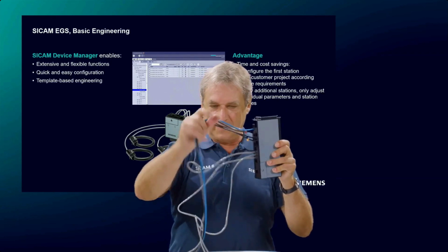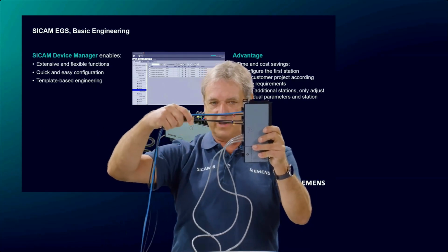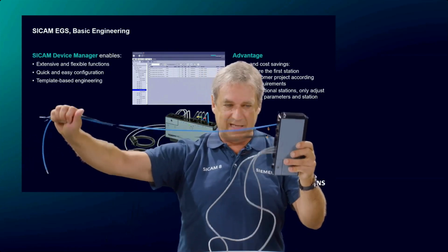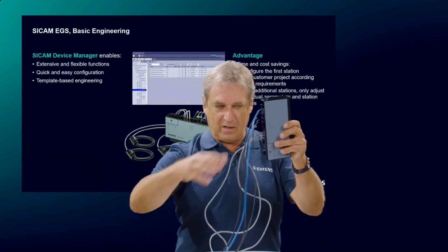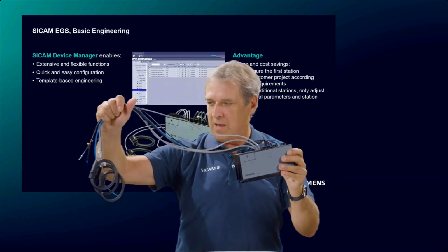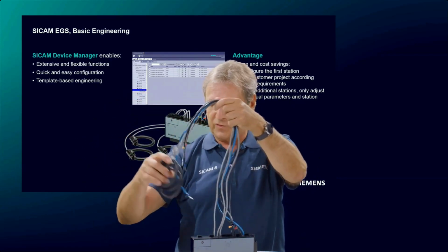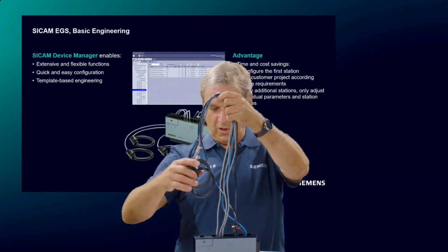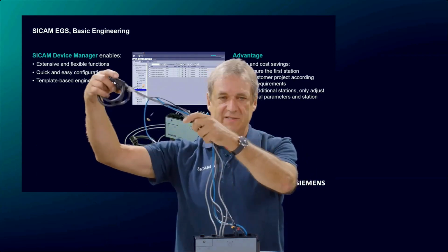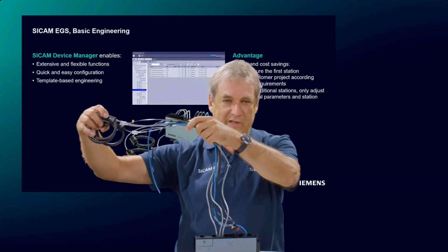Then the next topic, which we also explained. Here are the 4 wires for the voltage input. As you can see, it's approximately 1 meter in length. This device, as I have it here, is normally used for cable cabinets where the distance to the primary feeder or to the infeeder is not so long. But as explained before, this wire length to the Rogowski coils is also available with 3 meters, especially if you have, for instance, a low voltage station with a low voltage transformer.